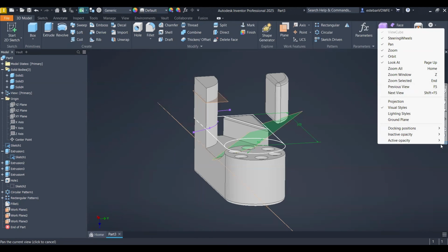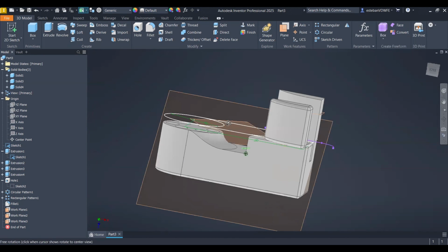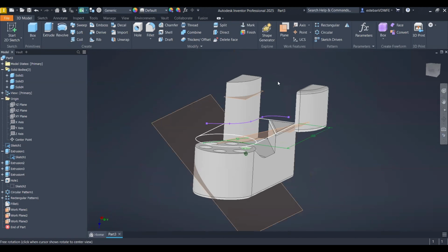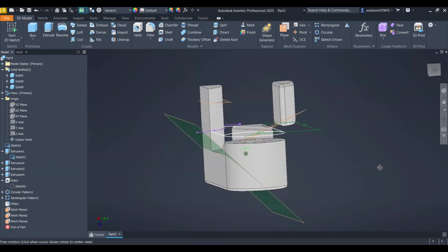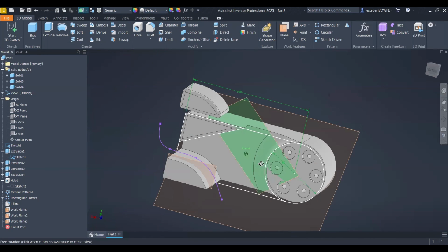So you click on this small arrow and you do the selection of what you want to have available. But yeah, how do I rotate like in SolidWorks with the scroll, right? Well, it is by holding the Shift key and then use the scroll as you used to do it. So you can see here the thing rotating.